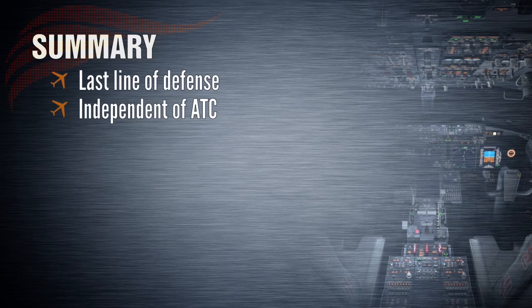This places additional burden on the pilots in an already high workload situation and does not immediately keep the controller in the loop. It does, however, mean that resolution advisories are issued regardless of ATC communication, making controller mistakes irrelevant so long as the resolution advisory is followed. Air traffic controllers, like pilots, are only human and do make mistakes, so TCAS acts as a further safety net.